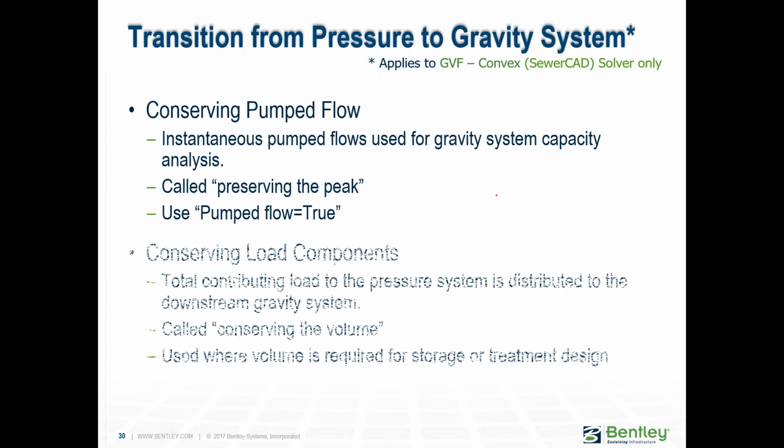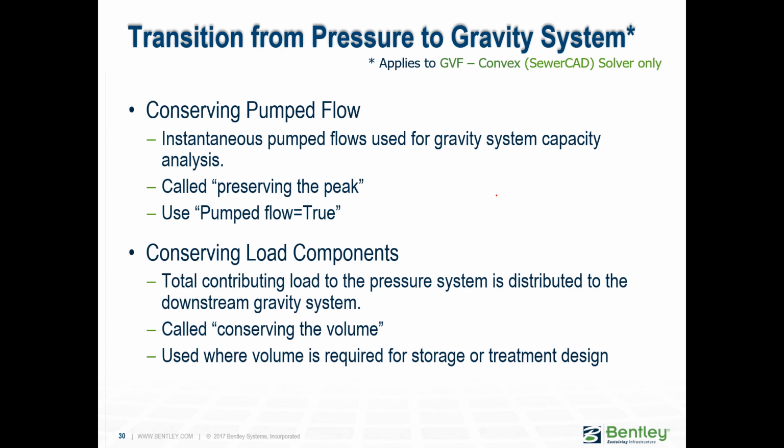There's something I'm always very hesitant about when I explain this, because when you're running this solver, if you run it in an extended period simulation, there's no problem. It will tell you how much the water goes up or down in the wet well and how much is being pumped at any time step. So in EPS, there's no problem. But when you're doing steady state calculations, there's an option in the SewerCAD solver to use or not use pumped flows.